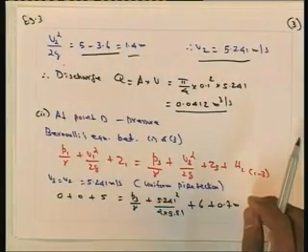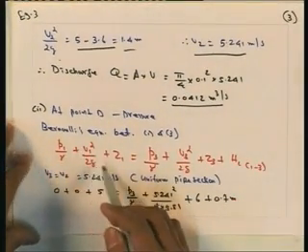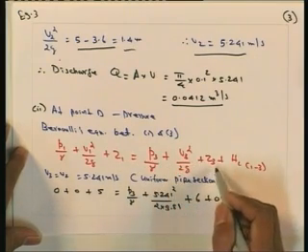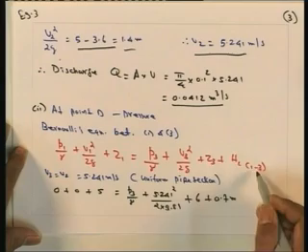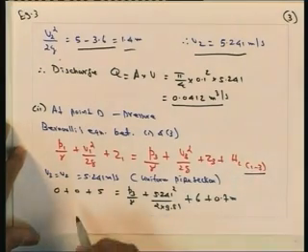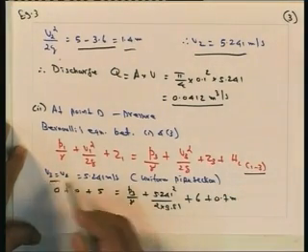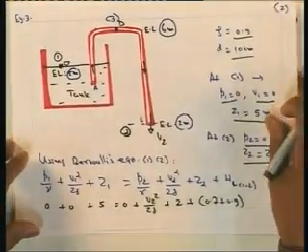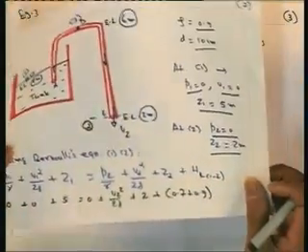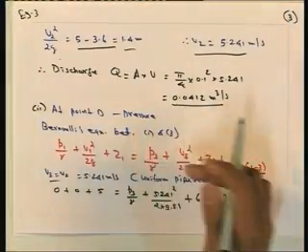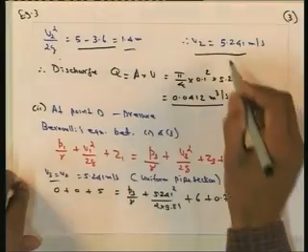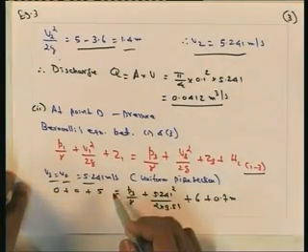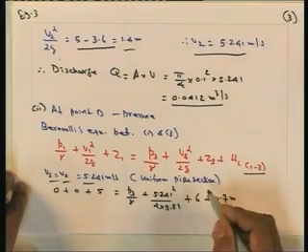If you apply the Bernoulli's equation, again P1 by gamma plus V1 square by 2g plus Z1 is equal to P3 by gamma plus V3 square by 2g plus Z3 plus HL, that means the head loss between section 1 and 3. Here you can see that since the siphon pipe is of the same size, the area of cross section is the same. So the velocity also, V3 is equal to V2. We have already found V2 as 5.241, so V3 is equal to 5.241 meter per second, since it is a uniform pipe section.